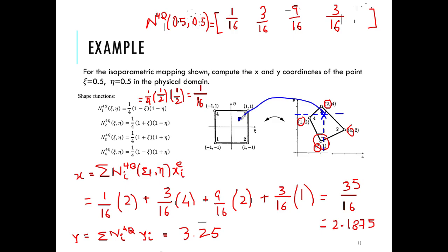That's what we know. So the usefulness of this isoparametric concept is that we can use these arbitrary quadrilateral elements, but instead of using them directly, we use our isoparametric representation such that we will find our temperature interpolation, if we so wanted to, T, at this point in our natural coordinates, and then using our mapping, we can know which point this corresponds to in the physical domain.